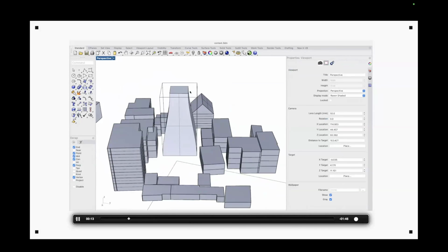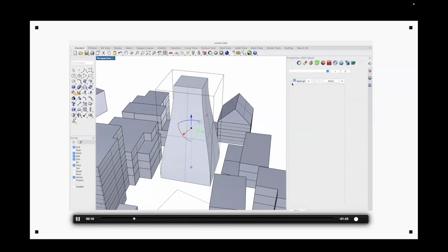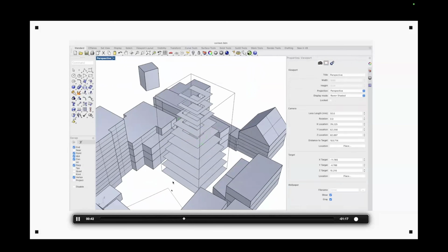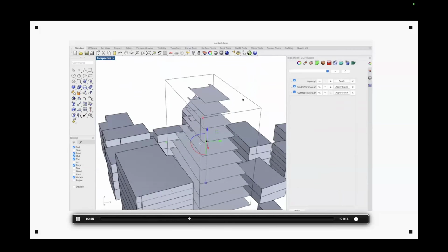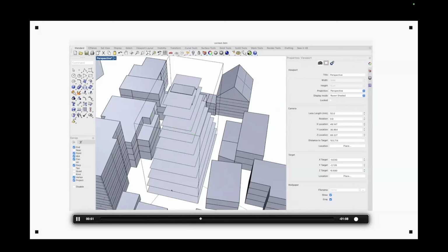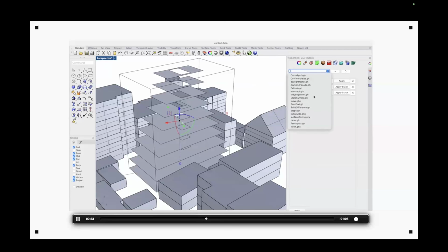But where it gets interesting is that now you can click on it and open it up, and you can get UI controls for this taper, but you can also add another Grasshopper file to it. So in this case, I'm doing a solid difference. So I'm trying to cut through the building geometry. So I select another object and then, you see, it's cutting through. So our original box is now run through the taper. And then the result of the taper is run through the solid difference. And now I've cut it into floor plates. And if I change the box that we started out with, all of the logic gets applied again and it updates. So here I now have basically a box that controls my model.